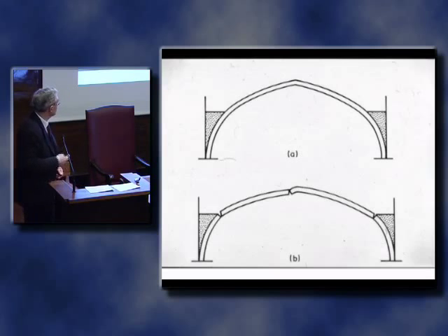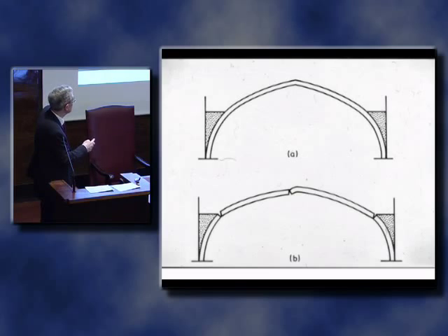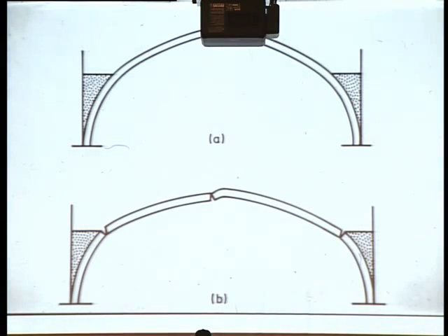And they occur because, considering first just a barrel vault built, this is actually roughly Gothic dimensions, the thickness corresponding to the span. And this is a two-dimensional arch, a barrel of uniform cross-section moving into the picture plane there. Notice that in order to get the line of thrust, the inverted hanging chain, that will never come down vertically here. It will spread out, and you need the fill in the vaulting pockets in order to take the forces out of the structure. Right, we build this vault.